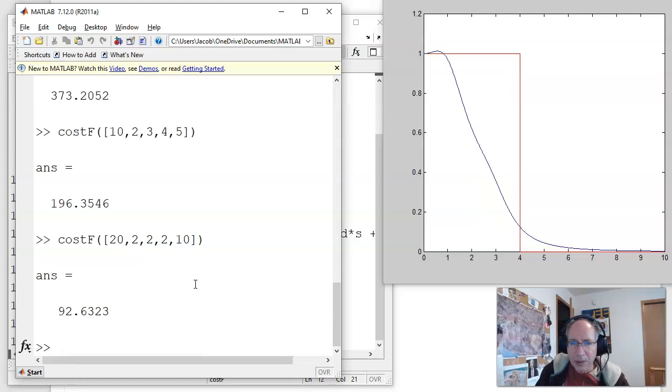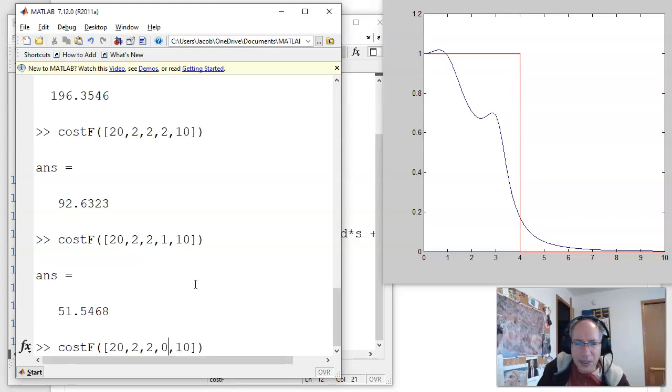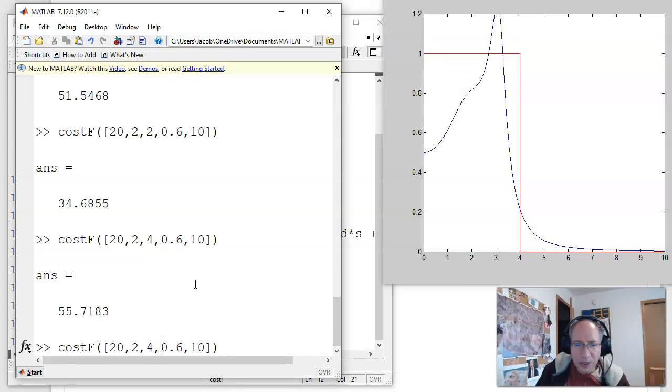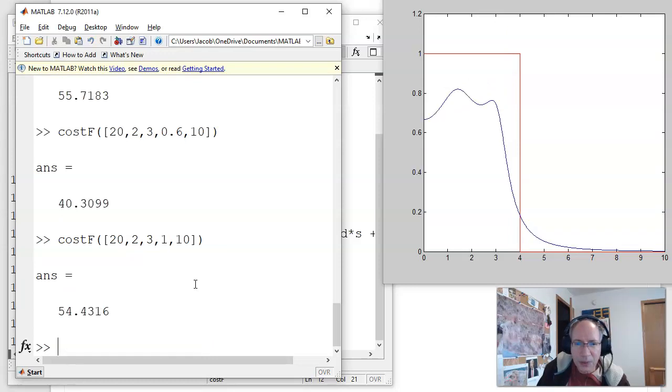Well, that's better. Let's take the pole at -3, move in the real part. So that'd be s squared plus s plus 10. Poles at -0.5 plus minus j3. Let's see, there's the resonance right there. Let's bring this down a little bit more. Take the pole at -1, move it out a little bit. Too much. Maybe take that second pole, reduce the resonance some, and kind of playing around with it, you can move the poles around and see what you're doing.